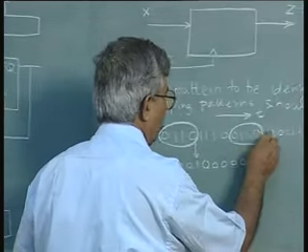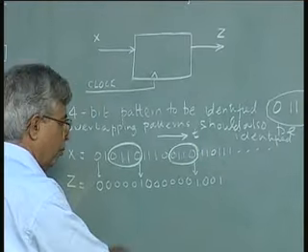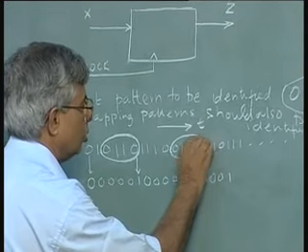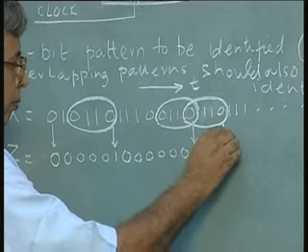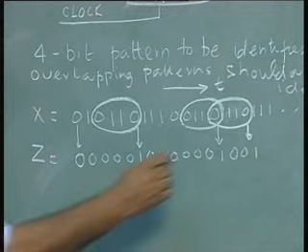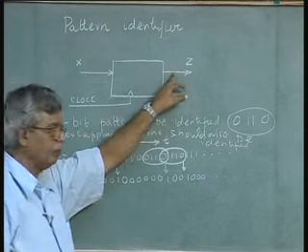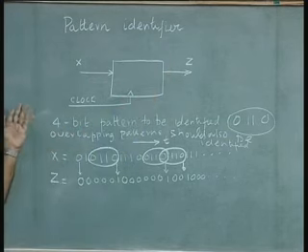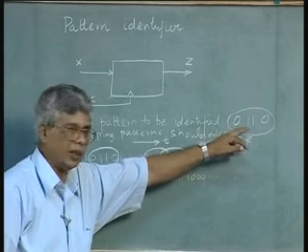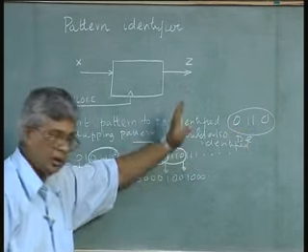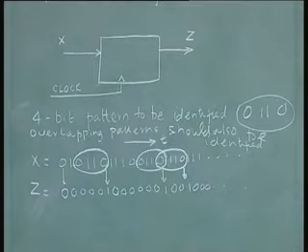So, now 0 1 1 0. I am going to call this a new pattern and give 1. This is what I wanted to say. Then afterwards of course zeros. So, one input, one output, one clock, of course there is only one clock. Whenever 0 1 1 0 occurs, output C should be 1 and overlapping should also be occurring. Now, this is the problem statement.